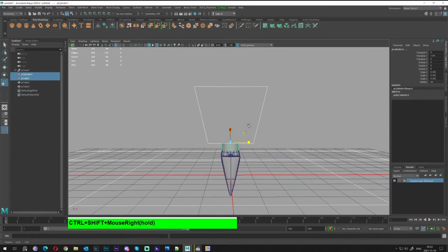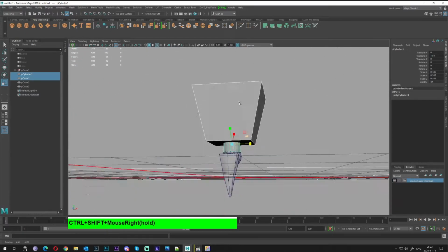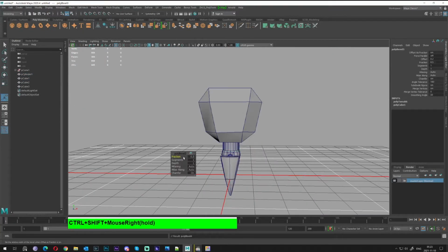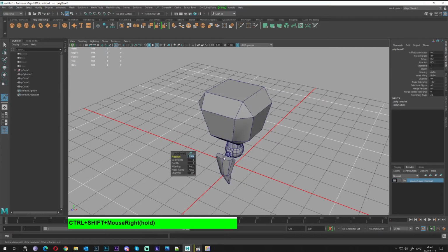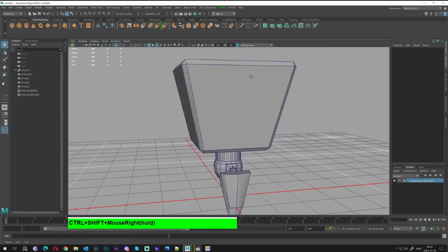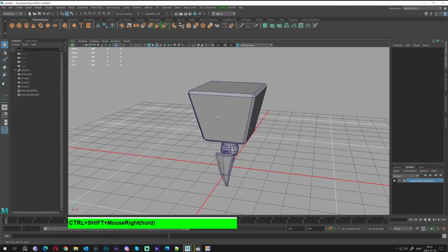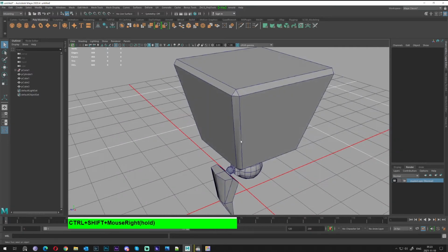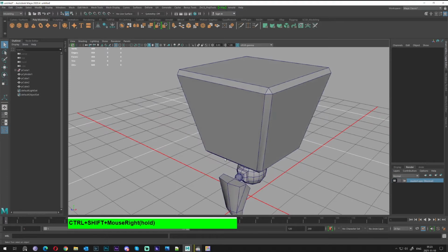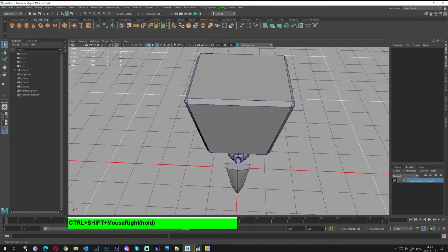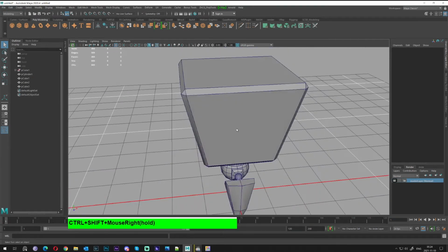Okay, so what we can do next, can select this cube and press Ctrl B in order to bevel that. I will go to point 1 in order to get these bevel lines, because if there is a 90-degree angle, as this cube has, it will be very difficult to render, because it will be straight lines.